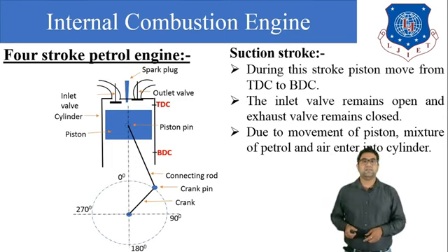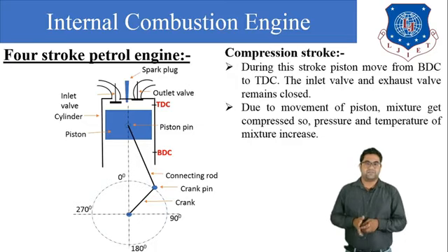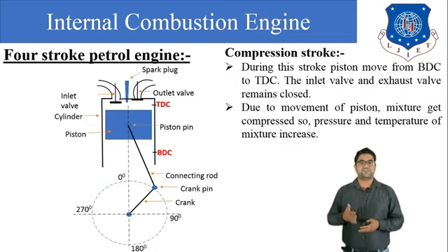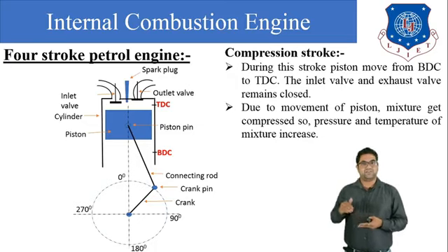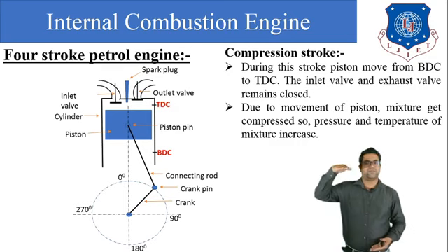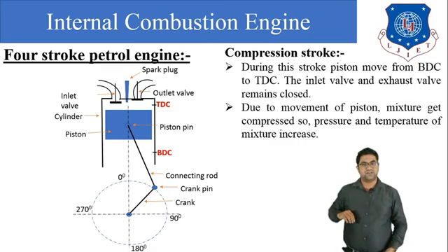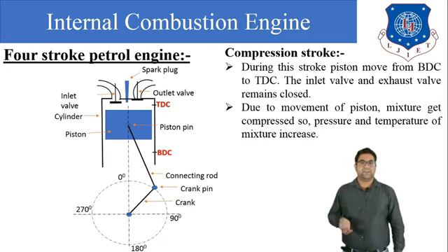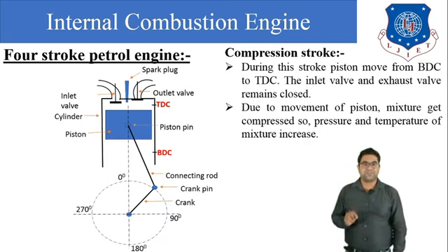Next is the compression stroke. What happens during the compression stroke? Initially the piston is at the BDC at the end of the suction stroke, so the piston travels from bottom dead center to top dead center. The petrol and air mixture already present inside the cylinder is compressed, and due to this compression the pressure and temperature of the mixture rise. During which, what happens?